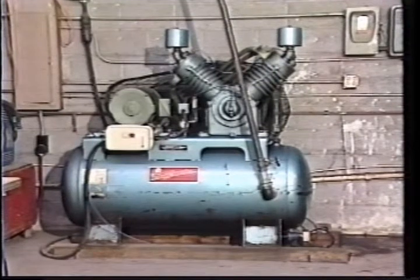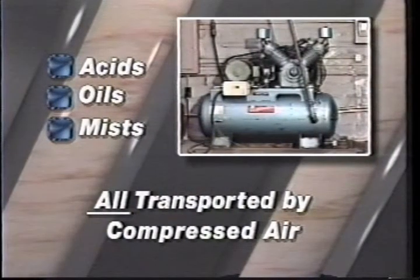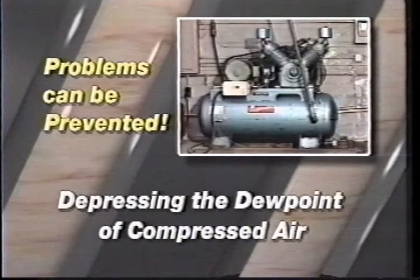Corrosion in pipelines can add to the particulates. Additionally, acids, oils, and mists are all transported by compressed air. Air cooled at the discharge point may mar surface finishes in painting operations, blasting media operations, and other operations such as cylinders, valves, instruments, actuators, and air tools. Many of these problems can be prevented by depressing the dew point of the compressed air.